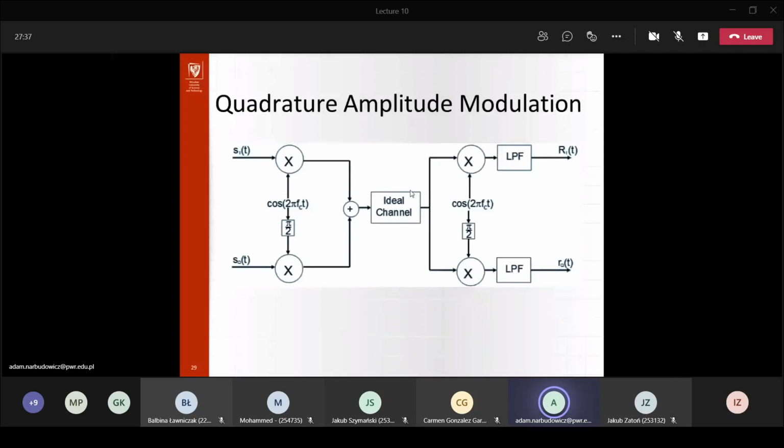The other possible problem that's actually more significant is if you get the carrier frequency wrong. If the frequencies are not well enough synchronized, what you would typically observe is that your QAM constellation rotates with time, right? Simply because frequency is the change of the phase over time, right? And if your carrier frequency is not perfectly aligned, you will observe this change. So then there are two factors that you can compensate for that.